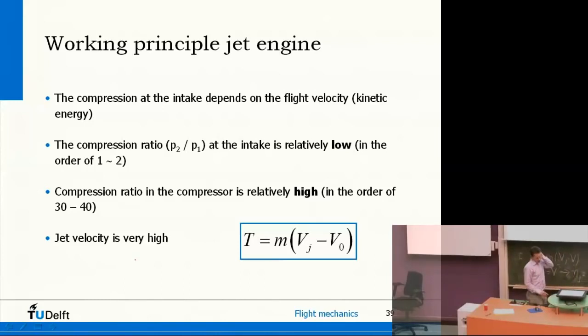Now, just summarizing, at the intake I said the air comes kind of to a standstill in front of the engine, and that makes the air pressure increase a little bit at the intake. But that compression at the intake is quite low. Maybe pressure increases by 50%, but it's really negligible compared to what happens inside the engine.